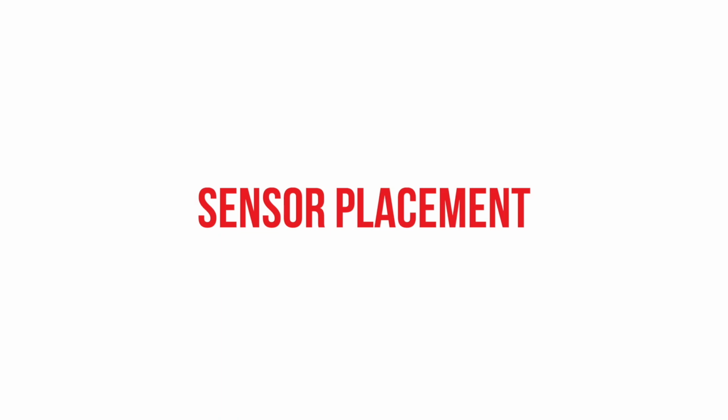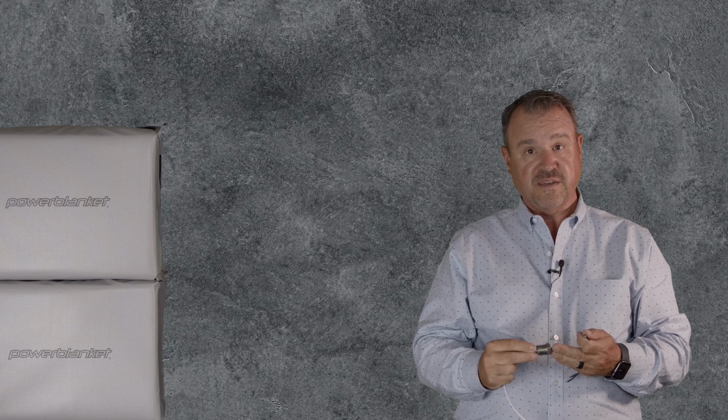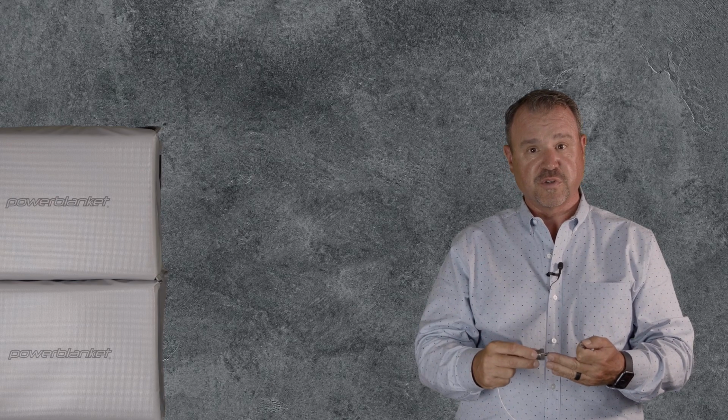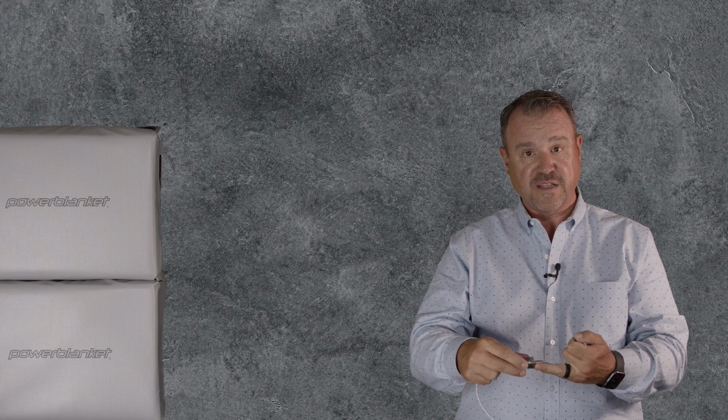If sensors are the most important part of the thermal loop, where you put them is actually even more important. Sensor placement means that I put this sensor in the exact area where the heat needs to be added. So if you have a surface that needs to be controlled at a given temperature, you need to make sure that sensor is right on that surface.